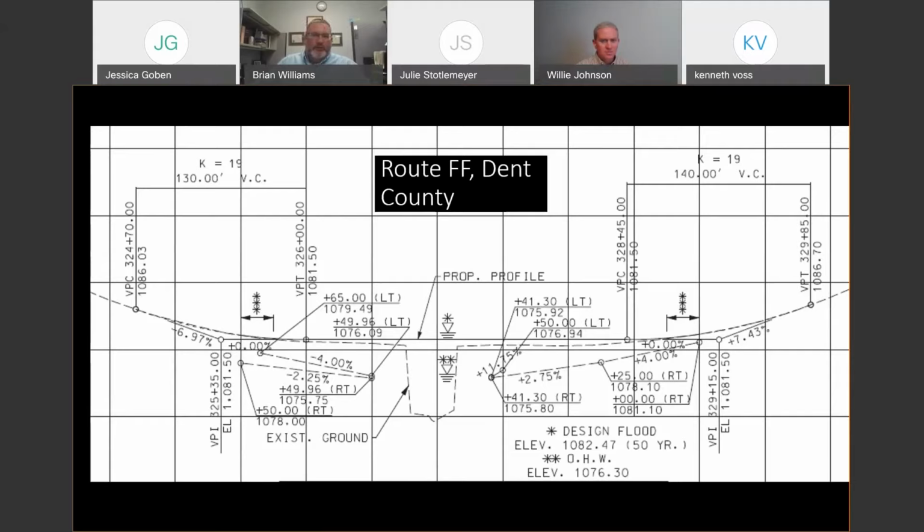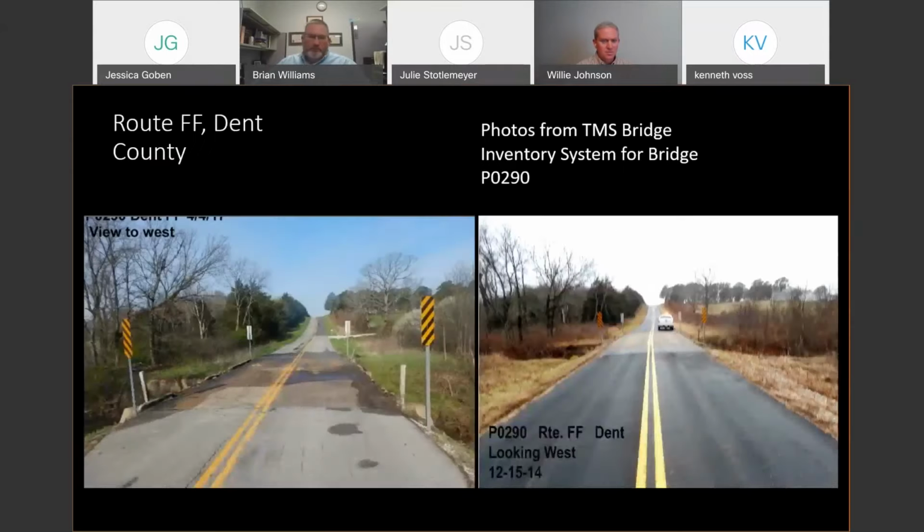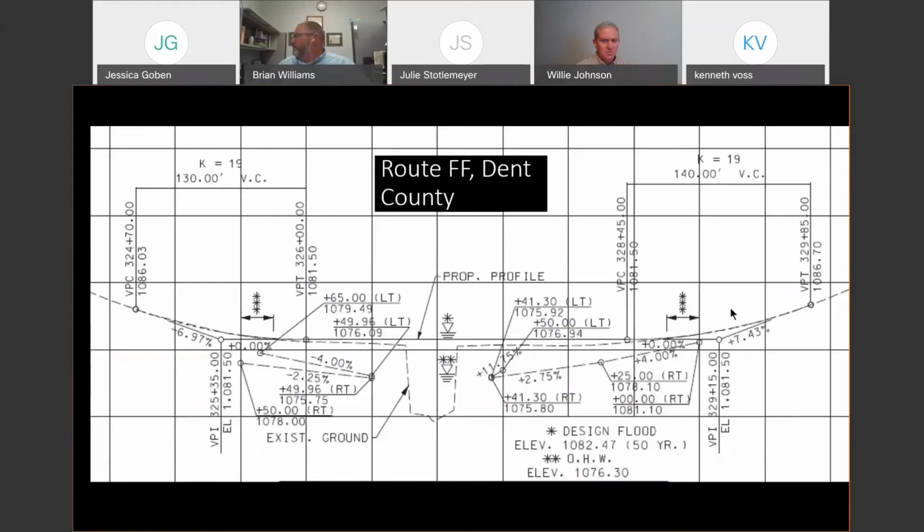As you can see, here's a ditch on the opposite side. It's an 11% grade. Okay, so oops, let me go back. You can see over here, 11% grade. Very short, but it is pretty steep. So definitely look at those and consider what you've got and what BMP you need.